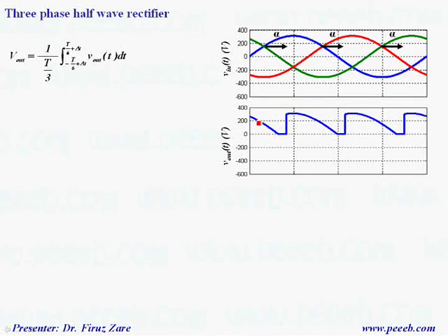We can find the output voltage for a resistive load when we have different firing angles, in which the thyristor is turned off for a short time. That means the output voltage is not continuous. So in this case we need to define these limits of the integral and find the equation. Similar to the previous description, we can find the output voltage based on this integral. The only difference is that this limit should be defined, which is basically T over 4.